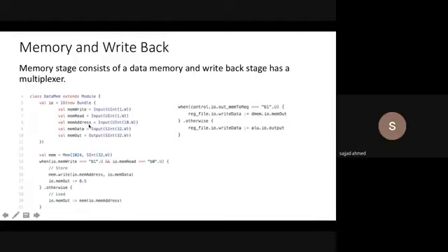The ALU calculates the address of the memory for accessing or storing data into the memory. Then memory data is basically the source for the register file, and then the output of the memory. We have asynchronous memory, as we saw in instruction memory, the mem construct. It is also 1024 lines and 32 bits wide. Then here is the selection when we write to the memory or read from the memory, based on the two signals coming from the control unit, memory write and memory read.